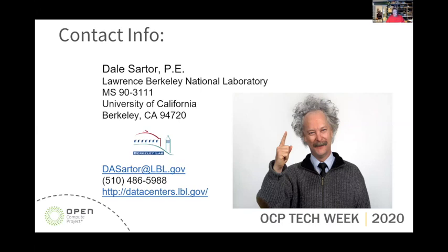But if there is a way to creatively work with these building blocks and cascade that thermal energy across multiple platforms, then all these platforms can sit within their own comfort zone, and you end up circulating a lot less liquid, which is much more efficient to cool because it's much easier to cool down 100 liters of liquid from 50 degrees C to 20 than it is to cool 500 liters of liquid in a delta of 6 degrees.